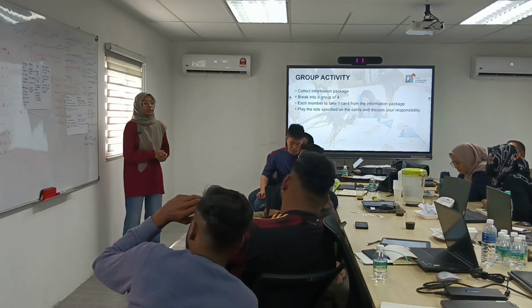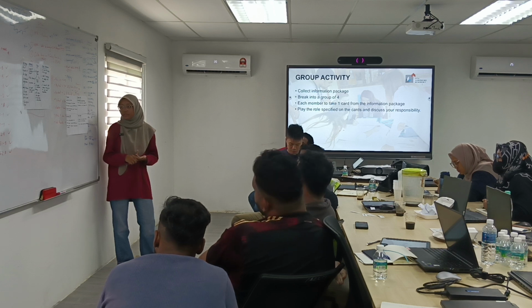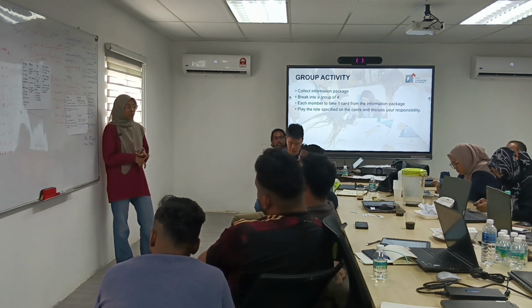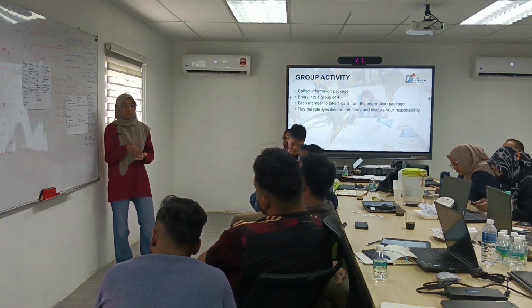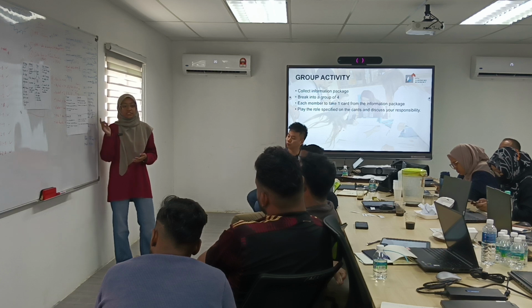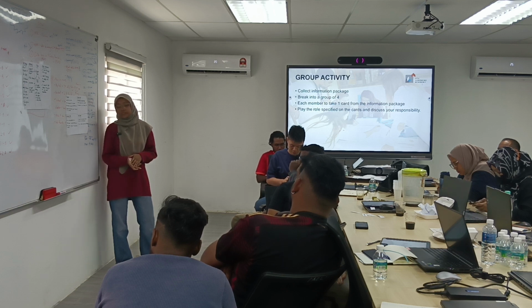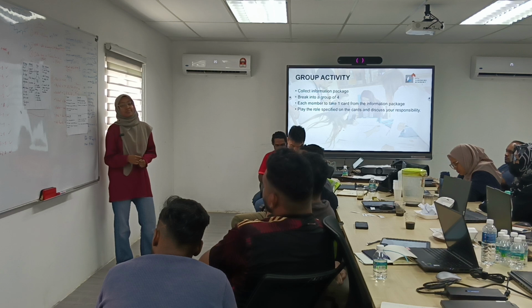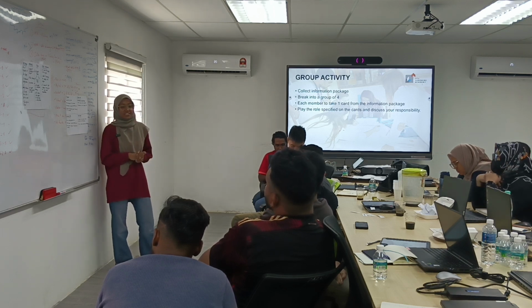So if the subcons are not following this approved shop drawing, material and method statement, then usually the IOW will make their comments, and sometimes if the installation is not as per the drawings, they will ask the subcons to rectify the installation, and also sometimes they tell us to stop concrete works, as the JDC2 engineers all know.